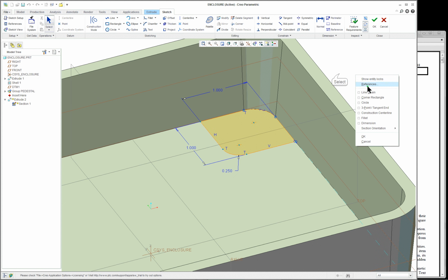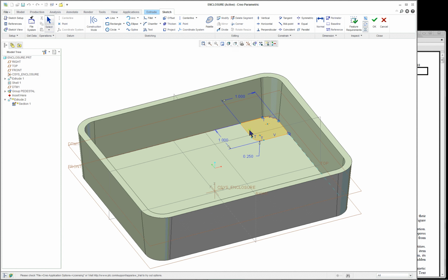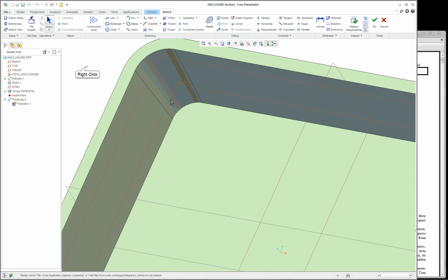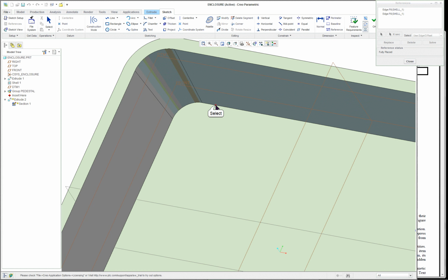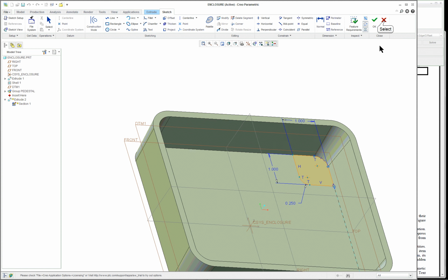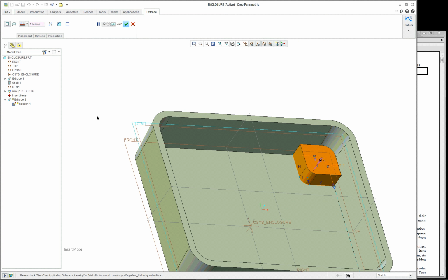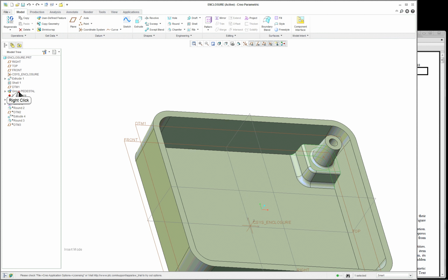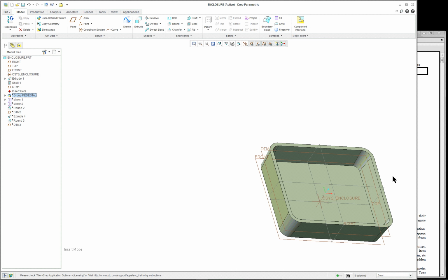The other thing you can do is you can actually go into your references and select these edges as references before you do your sketch. And maybe we'll do it on this side here just to show. Again, you can use edge, but this actually I think works better. Yeah, it won't allow me to do it. What's happening is we've got a lot of other geometry that we created, and it's referencing this information. So in order for me to do this at all, I can't use this pedestal information. I have to suppress it and do it from scratch. That's no big deal.